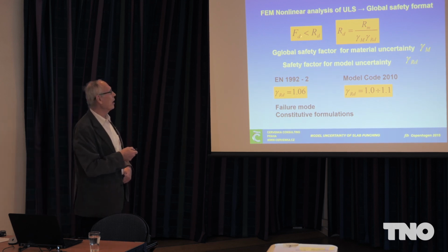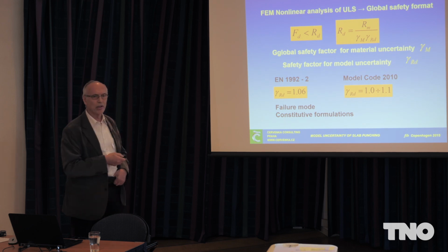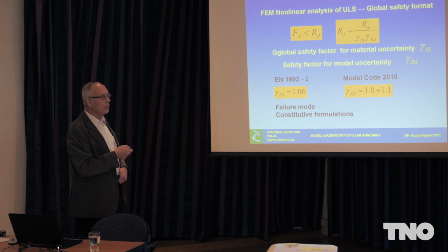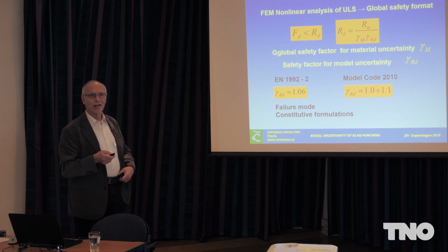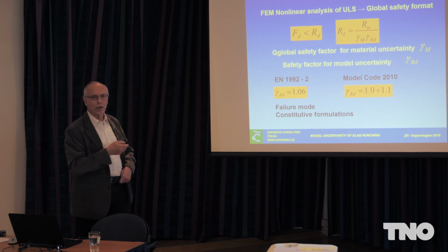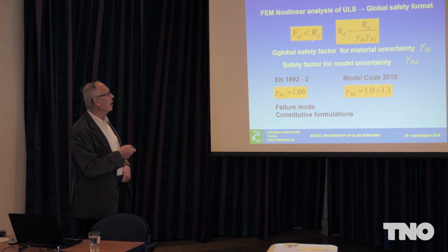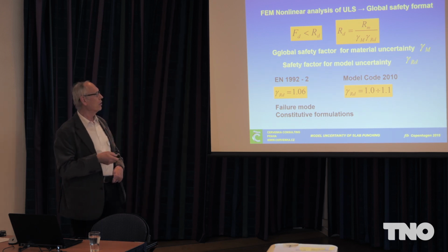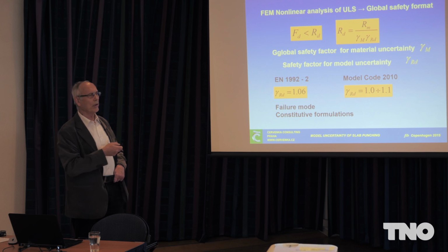We separate the action and the resistance or performance, so it is easier to distinguish the uncertainties. Furthermore, we may use a very simple model where the design resistance is the mean resistance divided by safety coefficients. This is basically the framework we use.